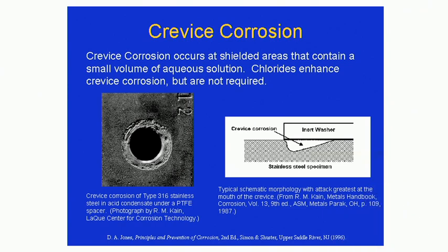This case is further aggravated if there is chloride in the environment, because chloride bleaches the oxide film. Not only that, chloride actually increases the corrosion rate to a large extent. So, the presence of chloride is dangerous, and crevice attack is the main form of corrosion in engineering practice.